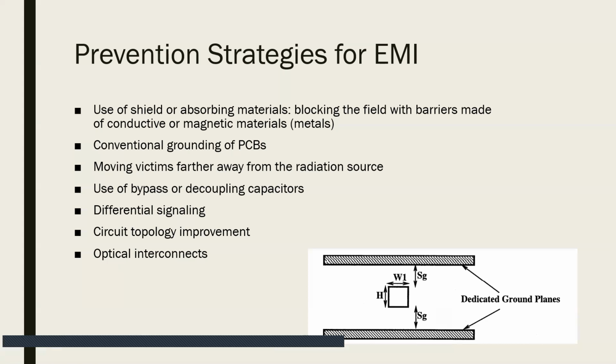People can also improve the circuit topology so that the circuit is designed to be immune to the EMI noise when it is modeled as an input referred noise. And finally, people are exploring the alternative of optical interconnects, and it's used in CMOS circuits.